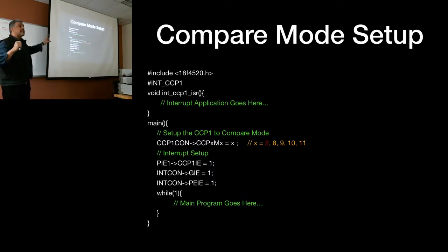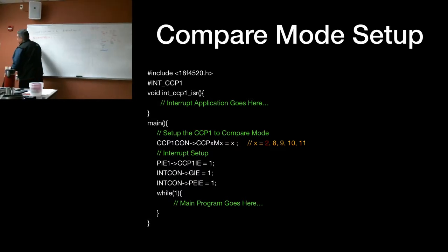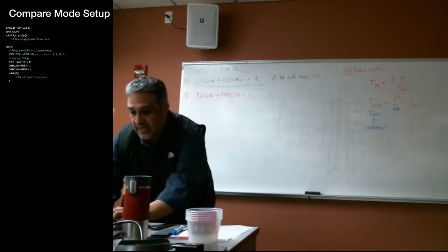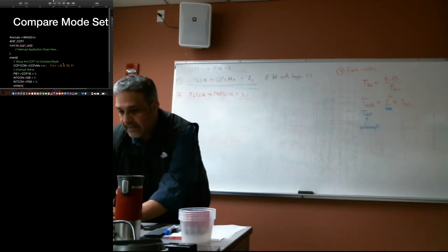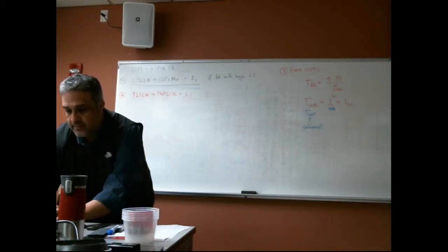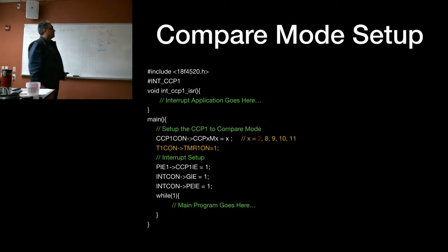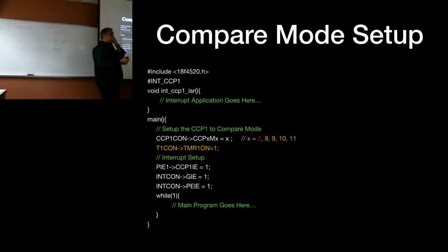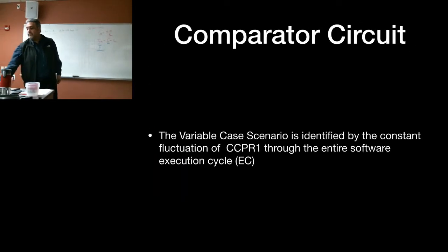So these are the minimum necessary conditions to get your CCP to work. Make sure that you add this instruction to it. In fact, I'll add it before loading this online. I'll add it here, to make sure that timer 1 is on. And that's all you need. System's ready. All right? Okay, now, here we go.